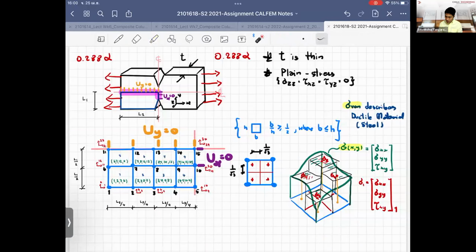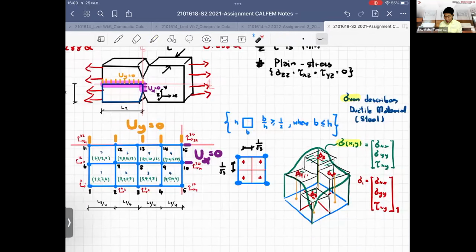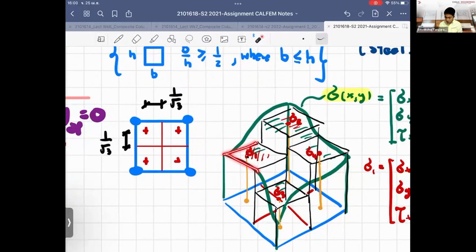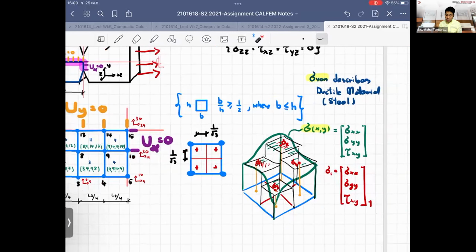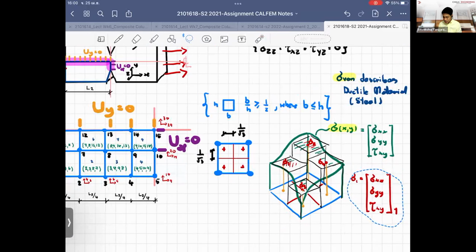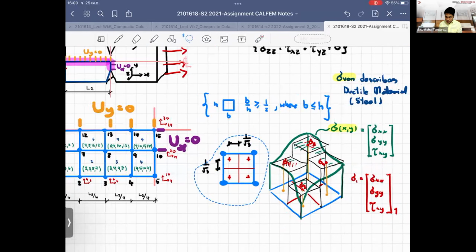You just take the resulting stress, or the stress at the Gauss point, and that value of the stress at the Gauss point will represent the approximation at each quarter of the element, as a constant. So we approximate the hypersurface stresses by using the piecewise constant fields of the stress that we have at the Gauss points. Okay, and this is the meaning of it.